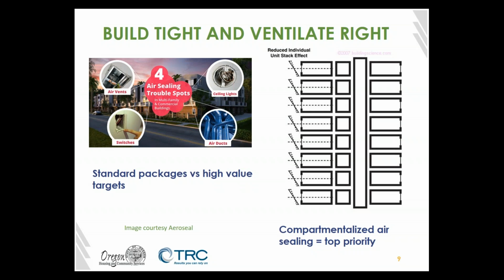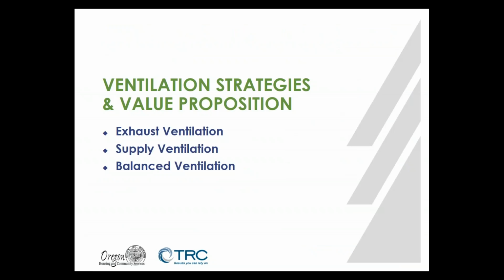Put the air where it belongs, the right air, the most quality air. So there's three different methodologies for mechanical ventilation: exhaust only, supply only, and balanced. And I'm going to walk through the differences between those three and what the dynamics are in multifamily buildings.